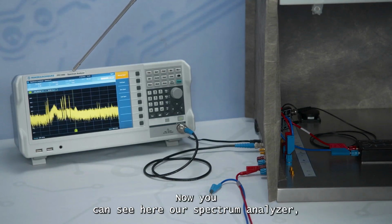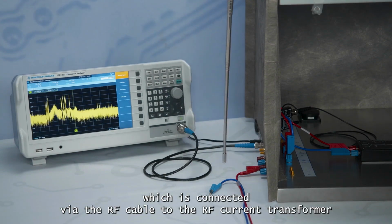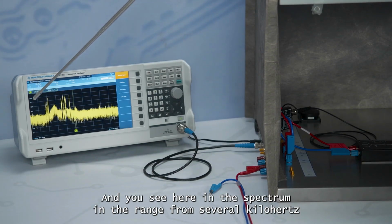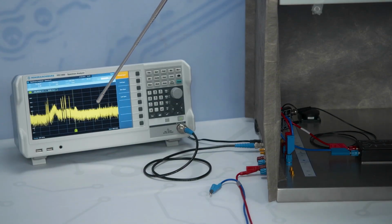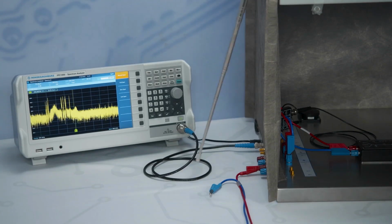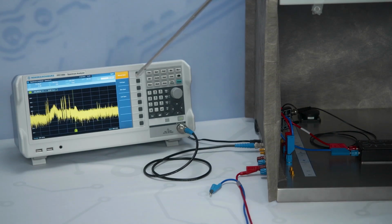Now you can see our spectrum analyzer, which is connected via the RF cable to the RF current transformer inside the shielding tent. And you see in the spectrum, in the range from several kilohertz up to 500 megahertz, a lot of disturbances coming from the environment because the tent is not closed. You see that the device under test is not powered, so these disturbances are definitely coming from the environment.